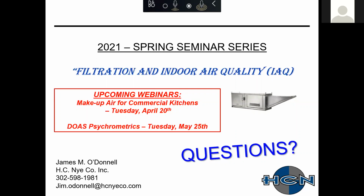And then if I can just interject with the air ionization maintenance. There are differences between the different manufacturers, with different maintenance requirements. The ones that use a bulb to create the air ions, those bulbs last about 2 years and then have to be replaced. So the UVC lights are like 8,000 hours a year. The bulbs are 16,000.